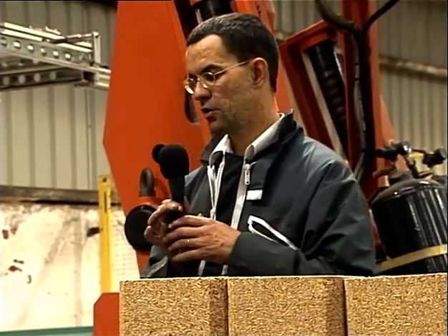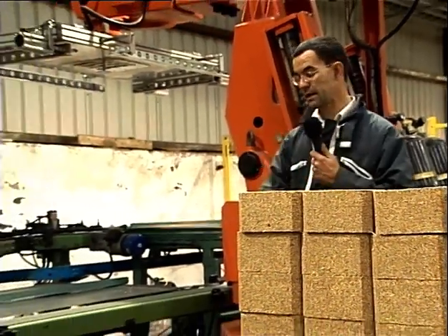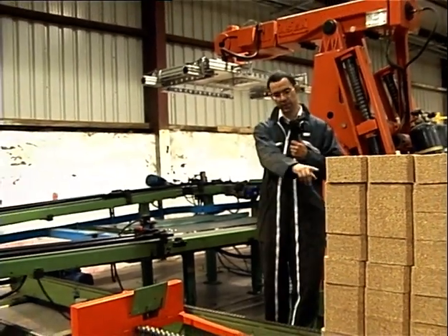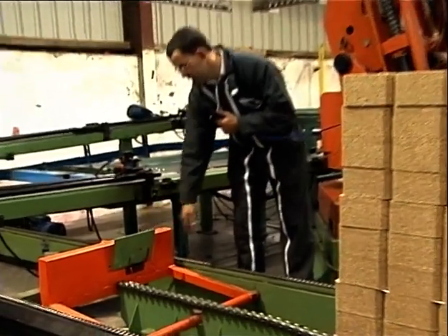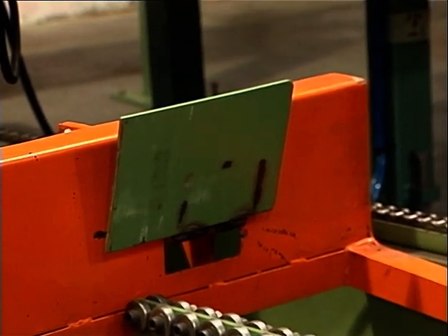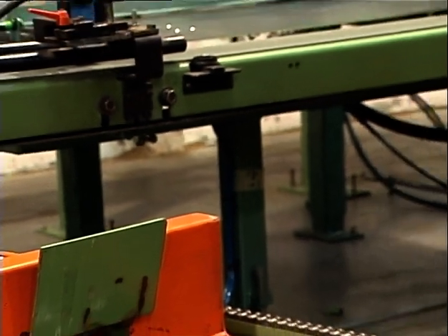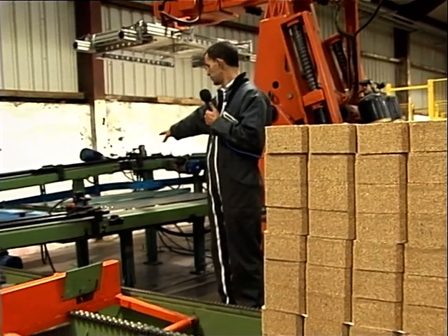As we have seen, we have started the robot on the electrical cabinet of the robot itself. Now we must also bring the stacks to the installation, to the pallet line. And how does the robot know that the stack has arrived? When we start the conveyors, the stack comes against this plate, and behind this plate we have an electrical contact that tells the electrical cabinet of the robot that the robot can start to take its first layer on the block table.